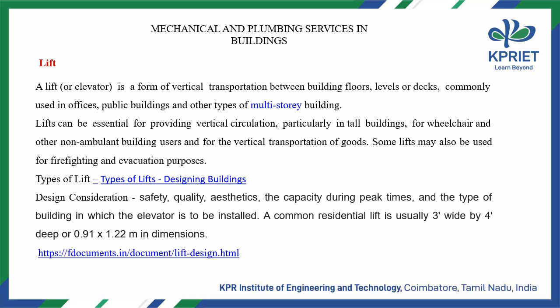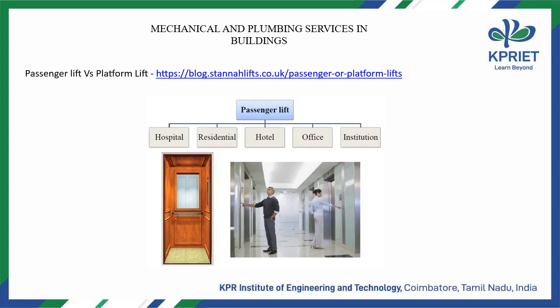Types of lifts. Design considerations: safety, quality, aesthetics, the capacity during peak times, and the type of building in which the elevator is to be installed. A common residential lift is usually 3 feet wide by 4 feet deep, or 0.91 x 1.22 m in dimensions. You can see in the picture the different types of lift.